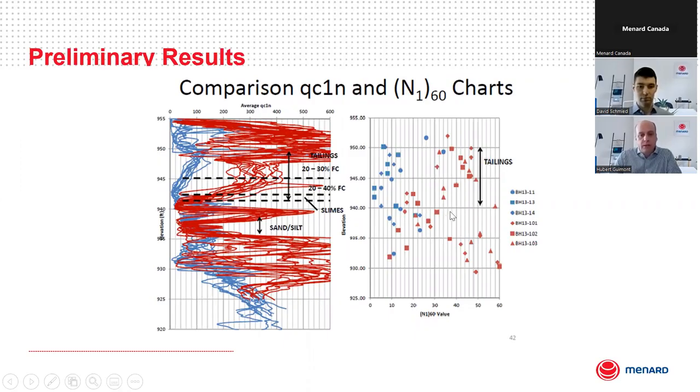Of course, when it's very slimy or very sandy material, silty material, the improvement is less. This is one of the characteristics of vibro replacement stone column: it still is a densification process, so the material needs to be densifiable for us to see an improvement.